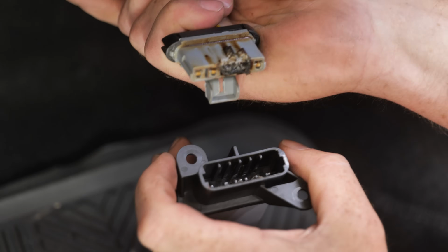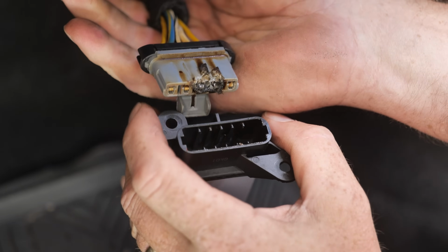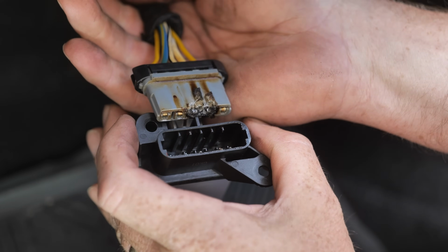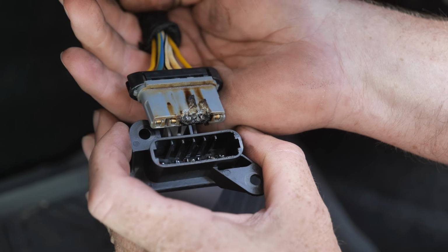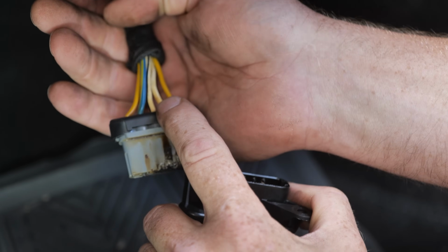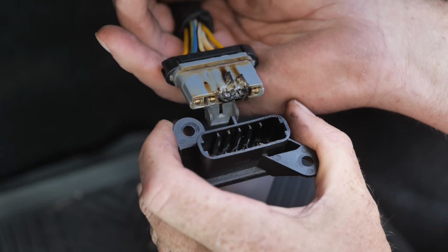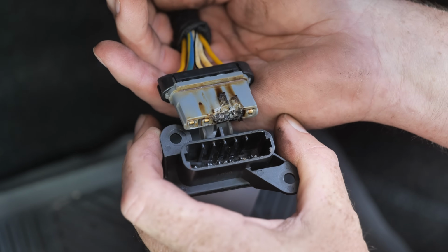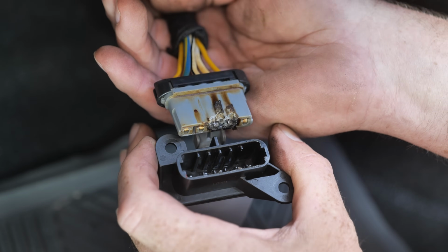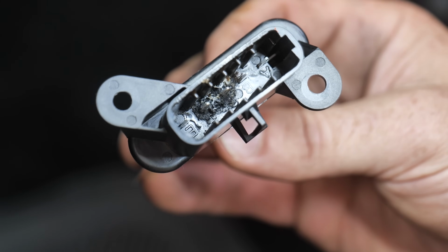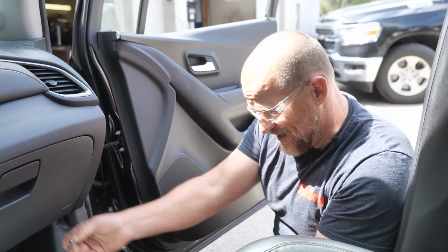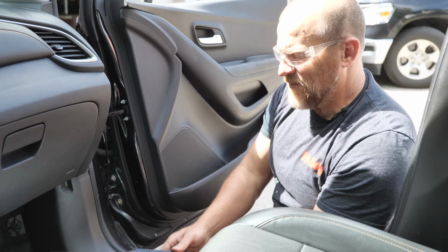Hold still. Dude. So was I correct in what I told you about the 2 white wires? I think so. Well, that's the 2 white wires. Oh yeah, it is. And look where it's burnt. Oh, it smells. You smell it? Yeah, it's cooked in there. All right, so what we want to do now, now it needs a connector. It needs a connector and a blower resistor.